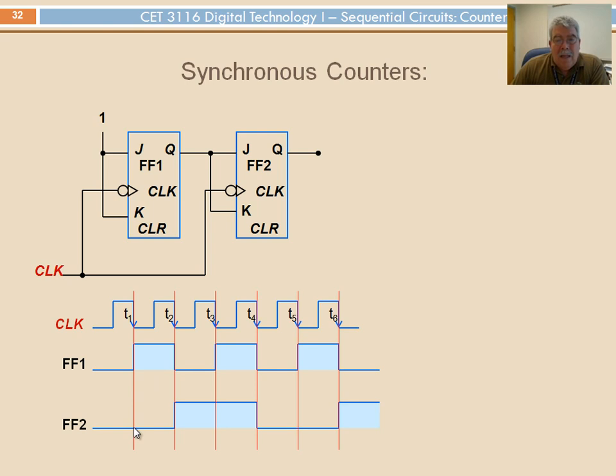Okay, and we have a hold from a 0. We're supposed to have this cleared, right? Both FF1 and FF2. And then now we read a 1. Okay, we are reading a 1, the next transition, and that corresponds to a toggle. In this case, we have a hold, the 1 stays, and then now we read again a toggle at this point. Therefore, we go to 0, and so on and so forth.